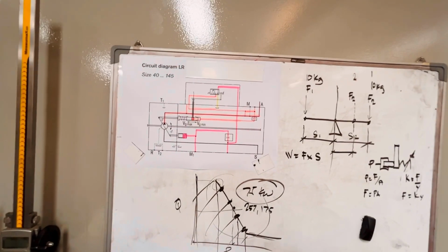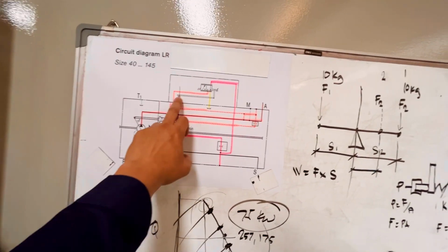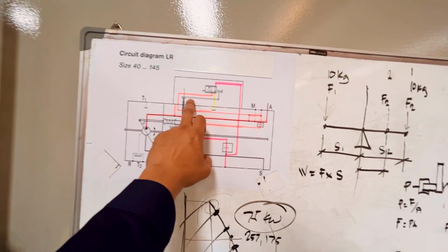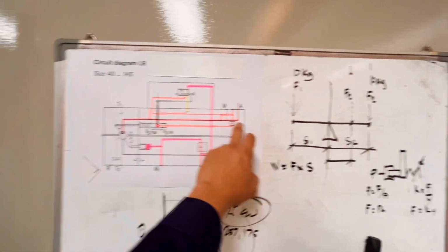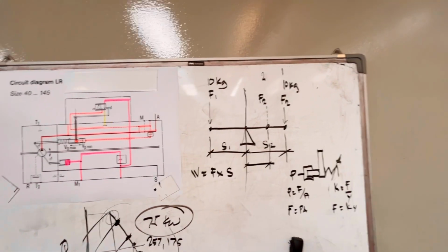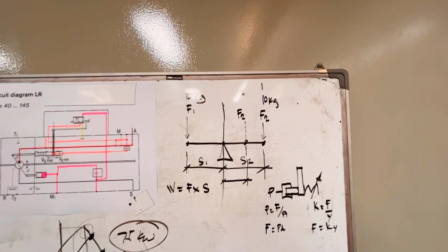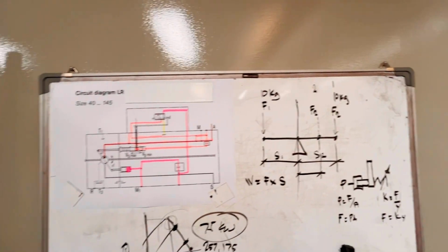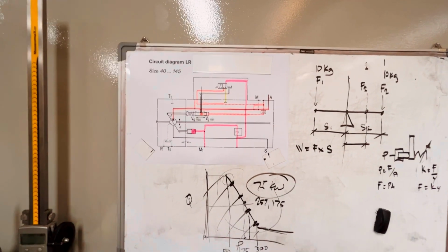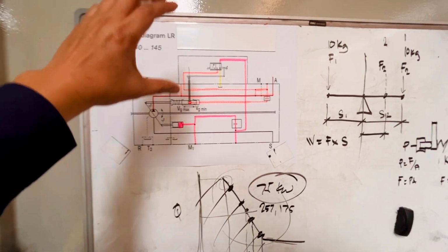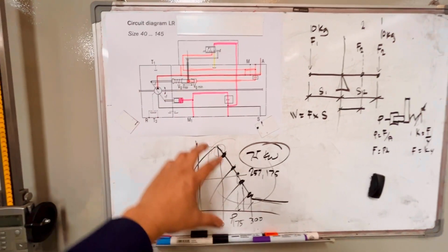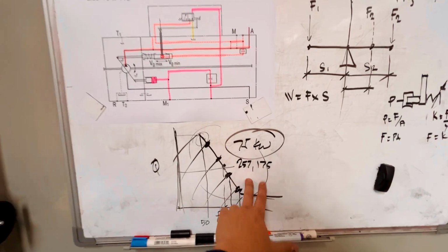Too easy. So when you see this kind of concept, this kind of drawing, remember this fulcrum or seesaw principle. It's the same. I hope you get it. The important thing here is to regulate the displacement of the pump so that your drive power will not stall.